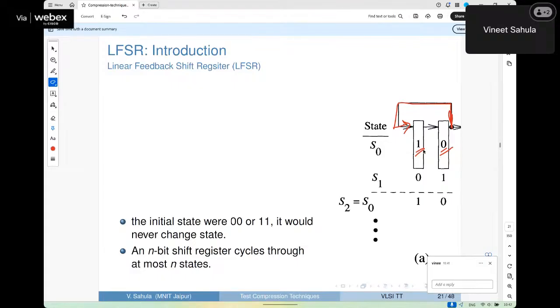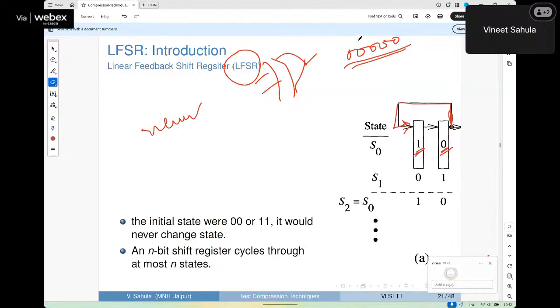If I store any non-zero pattern, let us not store 0, 0, 0, because when we do arithmetic, multiplication and addition with modulo 2, all zeros will always result in all zeros. So keep in mind the LFSR will never have the initial pattern as 0, 0, 0, 0.